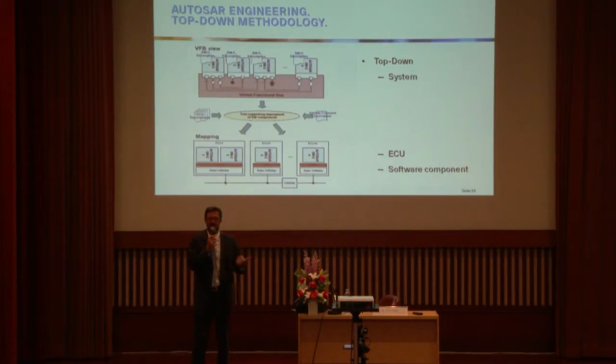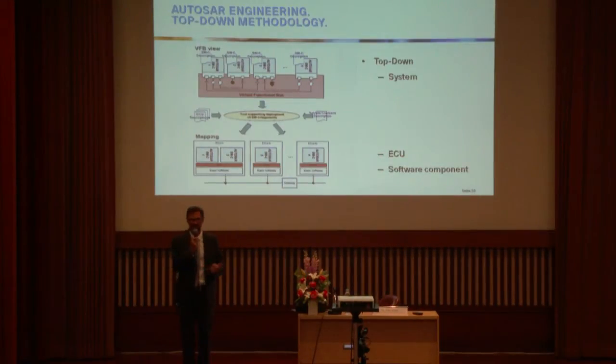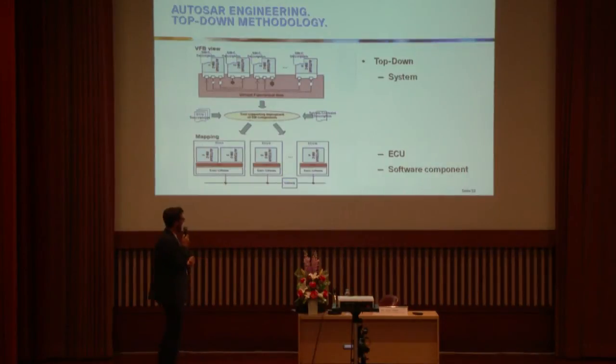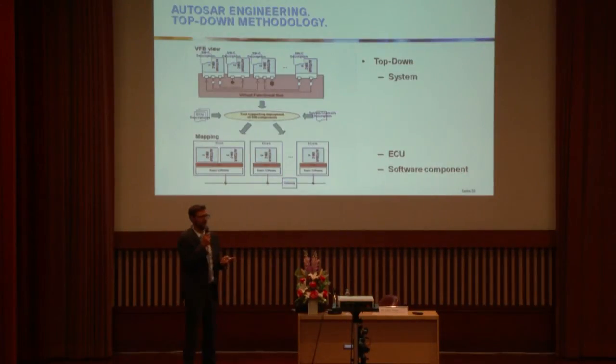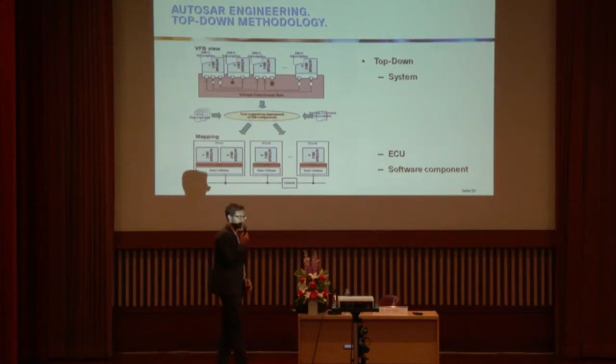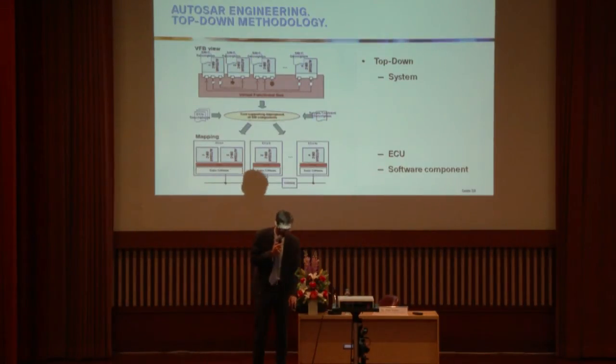So the virtual function bus knows which software component needs what data. This is specified in the logical architecture. And by the mapping of the software components to the control units, one knows which data have to be exchanged over the bus or only locally to the software component. And this mechanism is handled by the RTE, the runtime environment.